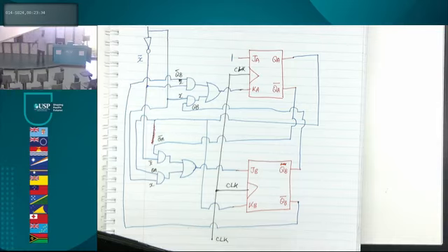Okay, according to that, you'll connect LEDs to your QA and QB. Right? So that's how you draw that circuit. In fact, this exercise doesn't carry much marks, the drawing part, because the hard part, the technical part, anybody can draw a circuit. The hard part is designing the circuit, which you had to do using the state diagram, state table, and getting the equations from the Karnaugh maps. Any questions?